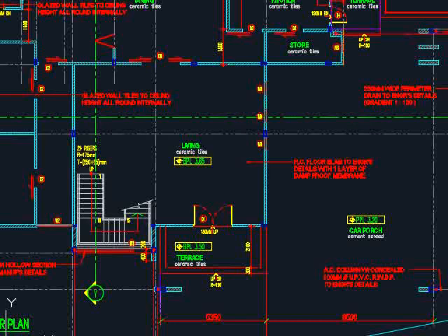Now you know that the lowest position will be the carport. Then there is a rise here in front of the main door, and then another rise for you to enter the living room. You need to be careful with the floor elevations, as this is going to govern your design later.